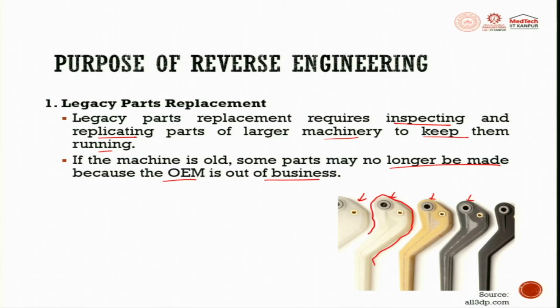For example, this component, if developed through polymer additive manufacturing, could have cost maybe 1,000 rupees, right? But we test the shape and exact dimensions, then we go to the metal part and try to produce the final component, which is reverse engineered. So this is an existing component, this is the new component that is being built. This is how we go about it.